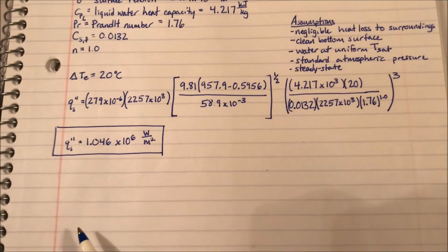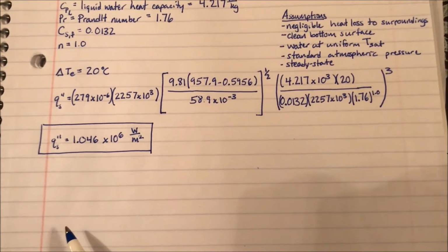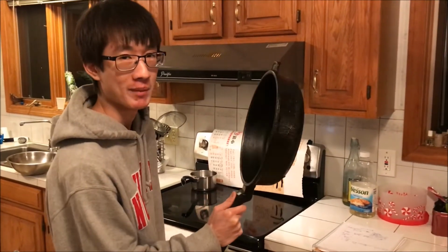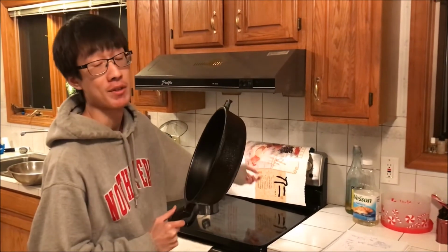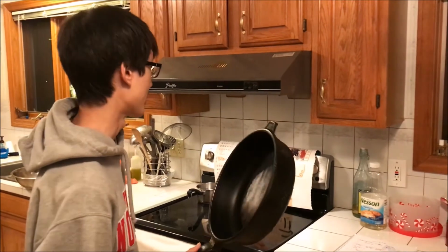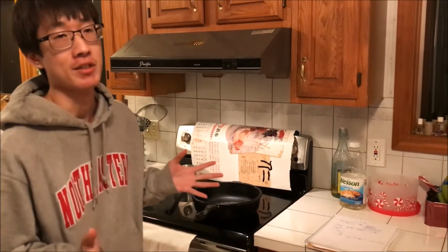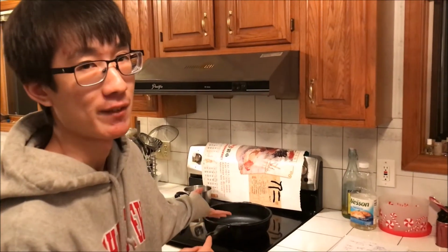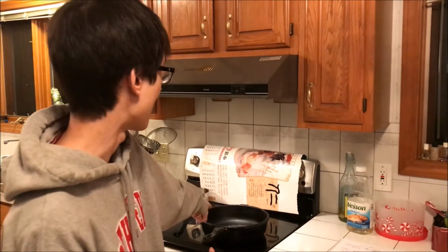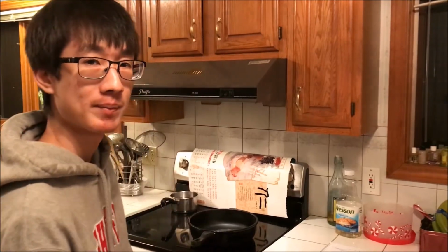Couldn't you just use the glorious internet to look up the heat output of that specific model stove? No. So now I have this cast iron pan that I want to cook my chicken with. However, I need to make sure that with this flux, this cast iron pan does not burn my chicken, which I happen to know happens at 180 degrees Celsius. So doing some quick calculations, knowing the thermal conductivity of my pan as well as the thickness, I can determine the surface temperature of this pan with the particular flux coming out of that stove.